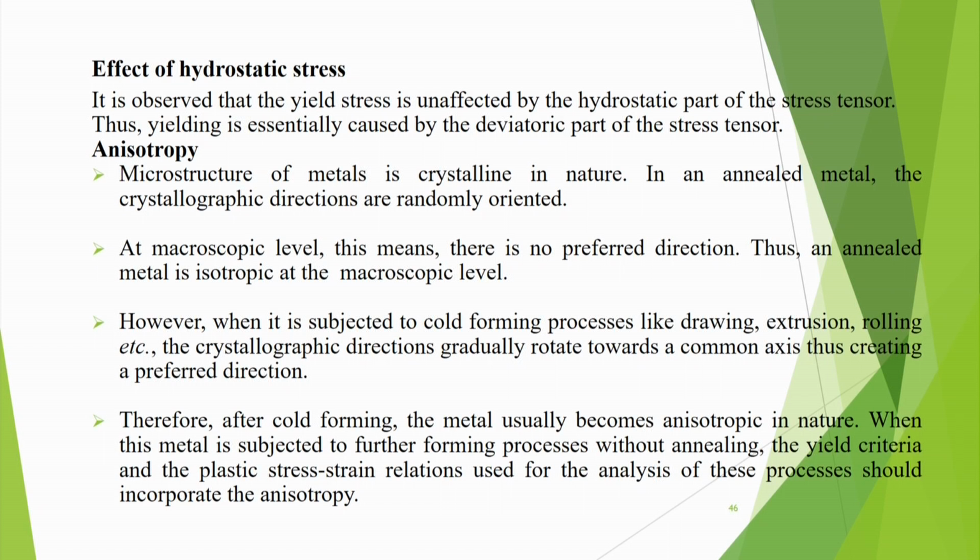Now, I will discuss what is the effect of hydrostatic stress. Before that, I must tell you what is the hydrostatic stress. As you know that stress has basically 9 components, and stress usually is symmetric. So, you can say there are 6 components of stress. Out of that, there are 3 stresses which are normal. Normal means direct stress, and you know that there are shearing stresses.